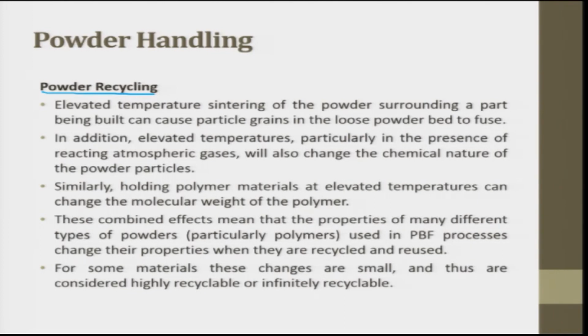Elevated temperature sintering of the powder surrounding a part being built can cause particle grains in the loosened powder bed to fuse. So this powder has to be sucked out and recycled. In addition, elevated temperatures, particularly in the presence of reacting atmospheric gases, will change the chemical nature of the powder. So we have to be very careful.